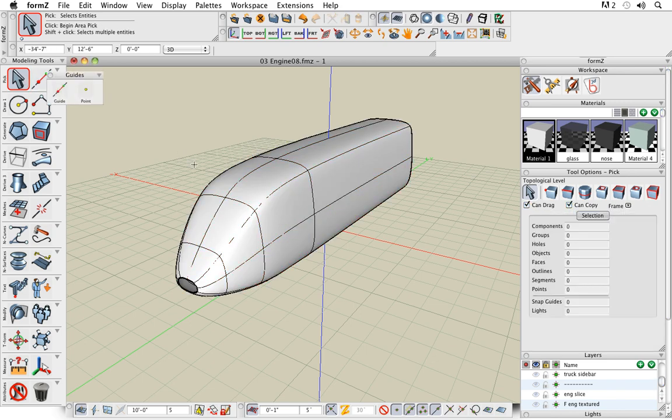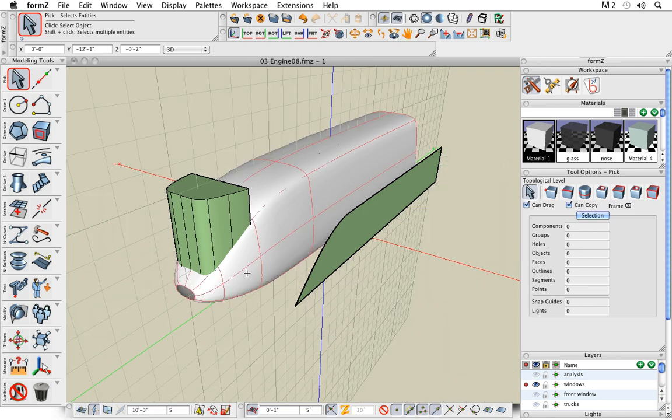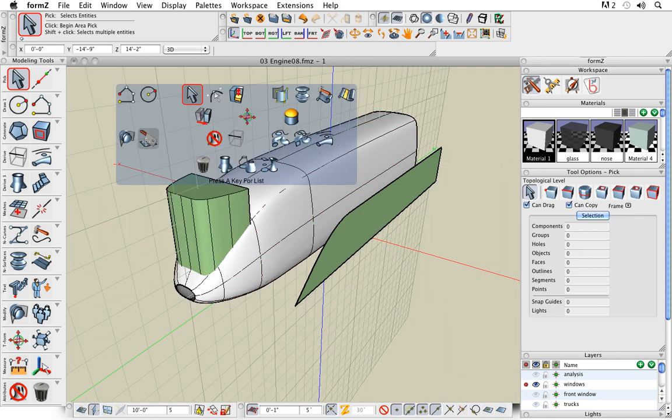What I'd like to do is quickly show how we can conceptualize our terrain by quickly slicing in some windows or doors into the object. Now that was done by just drawing some 2D shapes and some 3D objects. And then we'll use those profiles to actually slice right through the object using the slice tool.